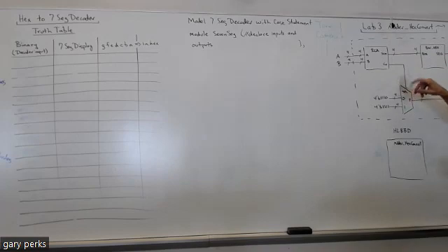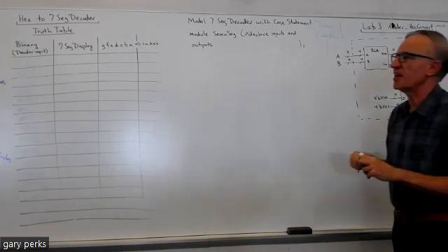The input to this decoder module is 4 bits. See, the 4-bit sum output of the RCA is connecting up to this BIN, which stands for binary input of this decoder. It's this bin underscore X. This is the decoder. You could call it 7-segment display decoder if you wanted to, but I chose to call it that.